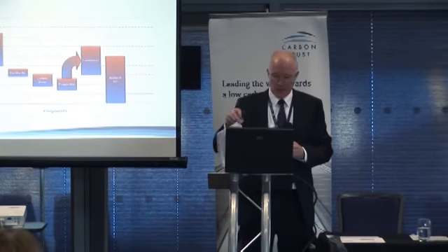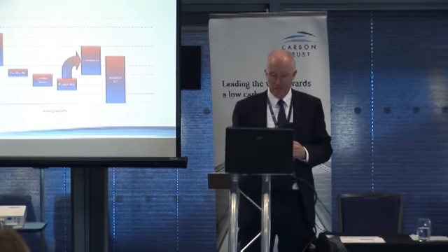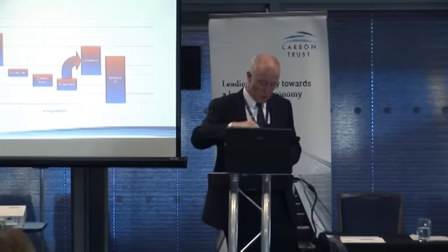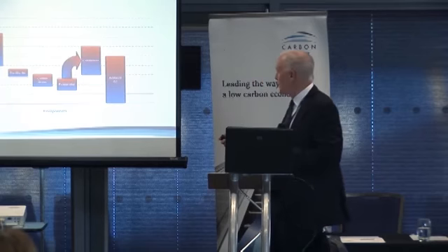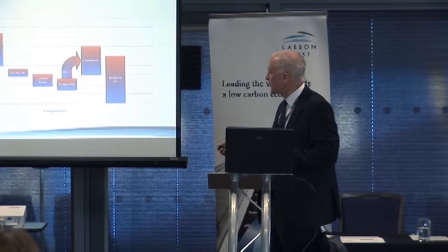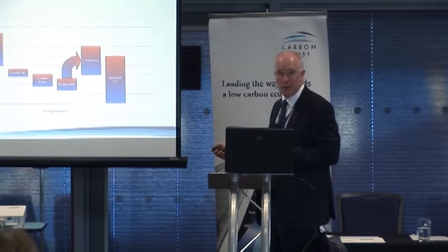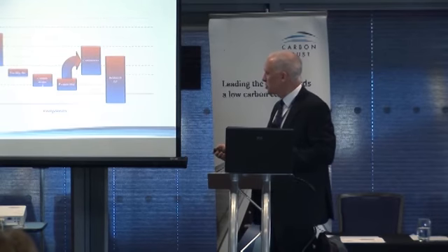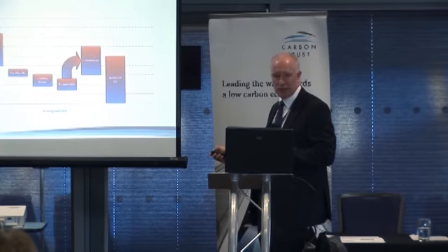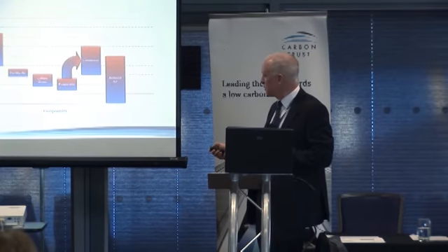In terms of refrigeration loads, what's important here is to just look at temperatures and why do we need cooling? Well, our processes are quite hot. This is a graph that's showing temperatures here against the components of the system. Processes are quite hot, but you're cooling these with a facility air that, we're recommending, 24, 26 degrees centigrade, something like that is what we're looking at. Sometimes using chilled water. Often that's set down as low as 6 degrees centigrade, but we're trying to push that up as much as possible.